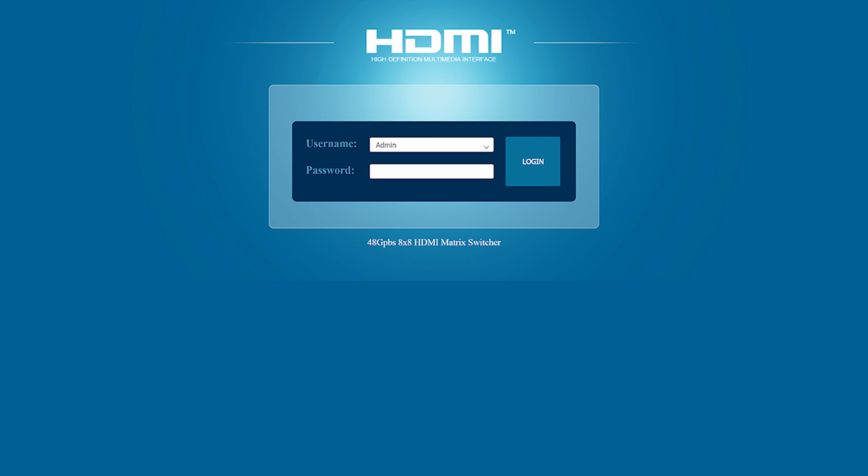Once you've opened a browser and made a connection to the video matrix through the LAN port, you'll be greeted by the main logon screen. You'll need to enter the right credentials to access the matrix. The default username is admin with a capital A and admin in lowercase for the password. When you've entered these, be sure to tap the logon button to enter the matrix.